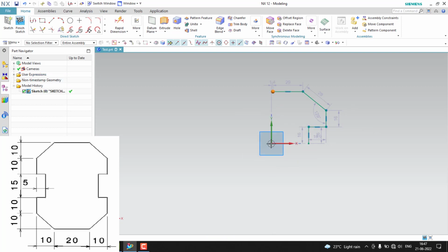So now you could see I need to make these two vertical actually, not the coincident. You can press Control Z because I do need to mirror, right. So again I'll select these two and make it vertical. Same thing for the bottom, it is horizontal. Okay, now you can select all the entities and mirror them accordingly.